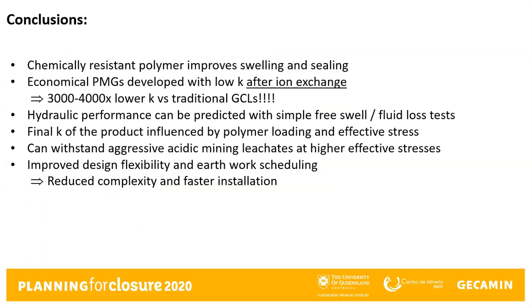So in conclusion, these new polymer modified GCLs show good chemical resistance to leachates. The polymer clay blends have improved swelling and sealing capabilities, and the materials are economical and have much more robust performance after ion exchange compared to traditional GCLs.